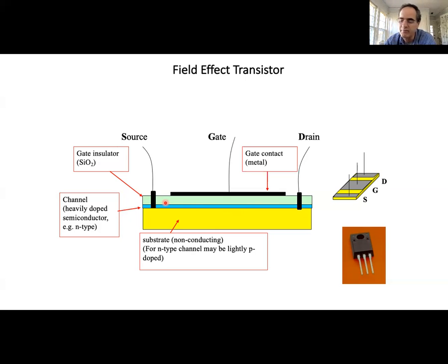Oh, I forgot the most important thing. The last contact. So this is a 3-contact device, just like the triode. We had the source and the drain, which are connected by the channel, but we have one more contact, the gate contact, which is a metal layer on the surface of the semiconductor. So this is a metal oxide semiconductor field effect transistor, or MOSFET. Let's see how this works.